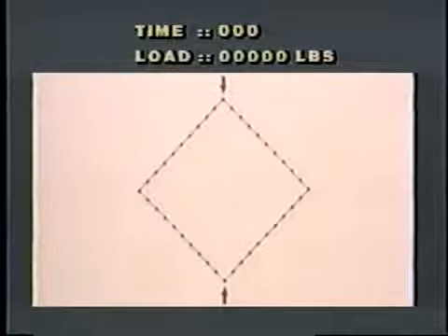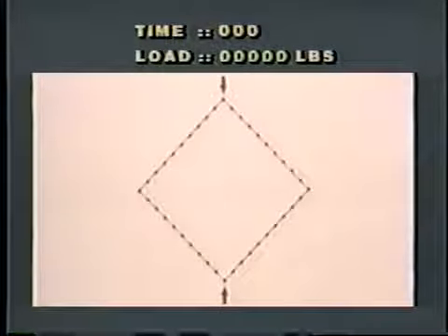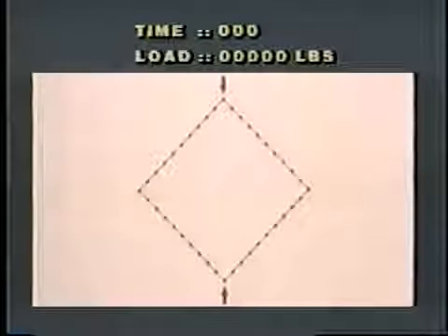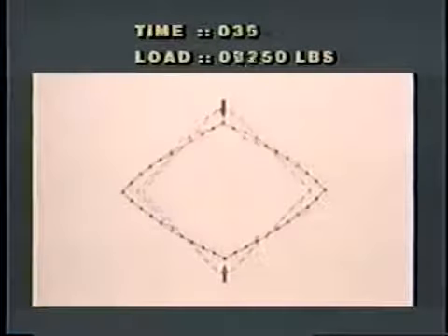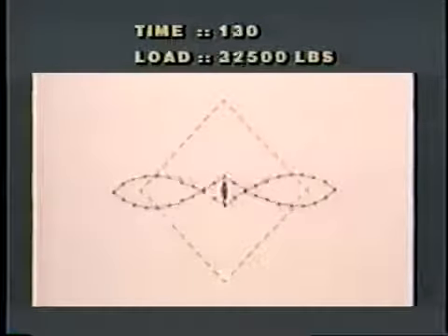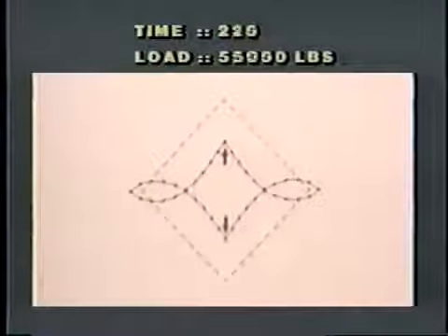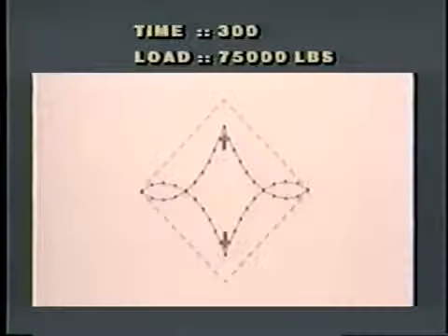You see above the frame a time and a corresponding load level. This is again a static analysis, and each time increment of 1 corresponds merely to a load increment of 250 pounds. Here now you see the deformations of the frame develop as the load is increased. The displacements are very large at the higher load levels. Of course, this is only a numerical experiment at the high load levels, but an interesting one that indicates in a simple manner what can all be done in finite element analysis. We will consider this problem solution also in more detail later in the course.